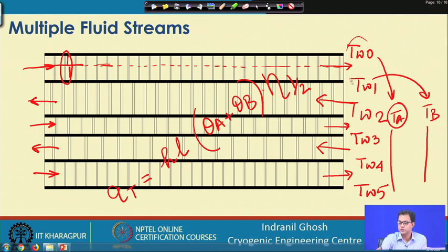In this nomenclature they are T W, in this nomenclature we have talked about T A and T B. Now, if that is connected by two fins, and we can show that when this T A equals T B, we will have a minima or a maxima at the middle of this fin, thereby depending on the temperature of the fluid flowing on top of it, we will find that the heat either is flowing from this wall to the fluid or fluid to the wall, but there is a minima at the middle of this fin.